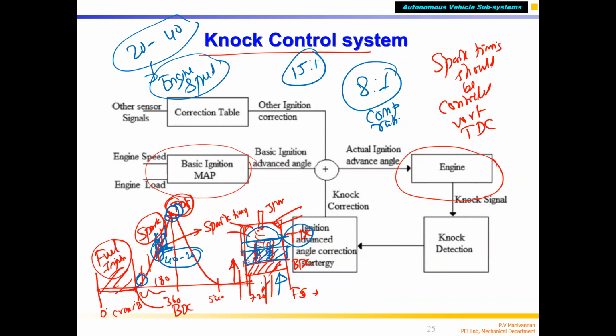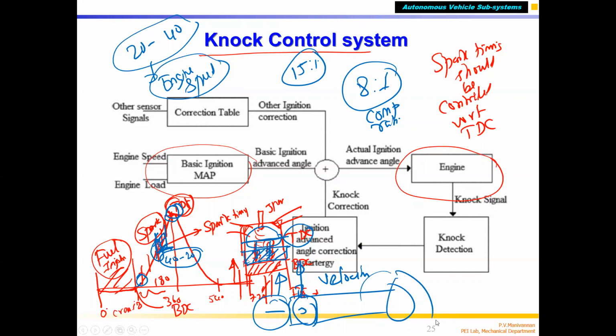We know that the piston is moving up and down with some velocity, piston velocity. Who is driving this? The crankshaft, with a flywheel, because you have a big mass attached to this. So it stores energy. This is what moves the piston up and down, the crank mechanism with the flywheel. The flywheel stores the energy, delivers it to the wheel, to drive the gearbox, but also it is moving the piston up and down, except in the power stroke. That is the third stroke in a four-stroke engine, correct? So that is why the 30 to 40 degree?